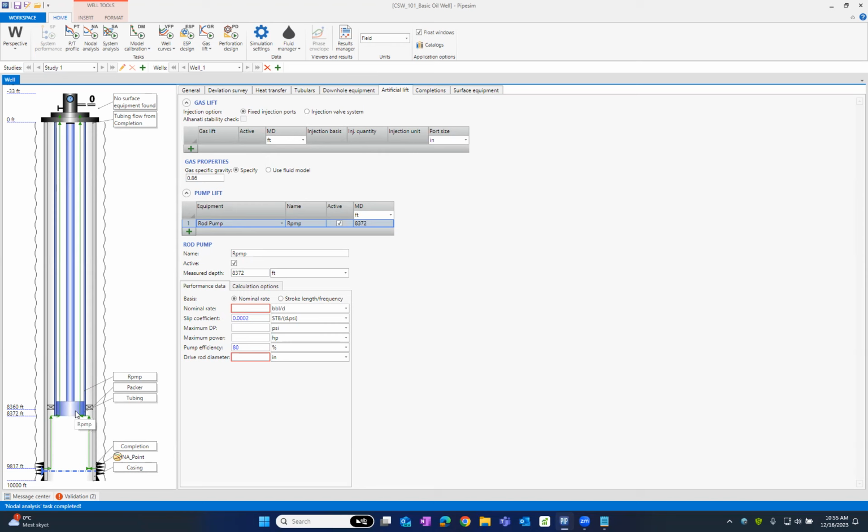One opens at the bottom, one opens at the top. When it goes down, the bottom valve will open, so that it holds a certain volume, then the bottom valve will close, the upper valve will open, and while it moves up, it will push the fluid. And as I said, it's classified as a positive displacement method, and you will see it everywhere.